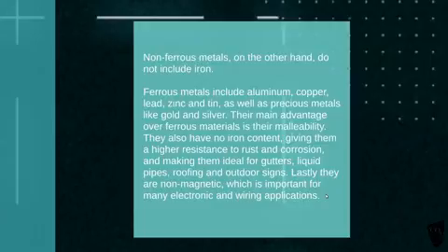possibly. The main advantages over ferrous metals is they're very malleable, they're workable. They're a little softer to work with, you can hammer them and bend them and shape them much easier. They've also, because there's no iron content, they don't rust very quickly. So they're ideal for areas where they're exposed to moisture or in aquatic environments. And we pick up gutters and things like that. Copper liquid pipes you'll find quite often. Roof sheets, wall sheets. And they're not magnetic. So again, you can go in and check it with the magnet out of your pocket if you want to.